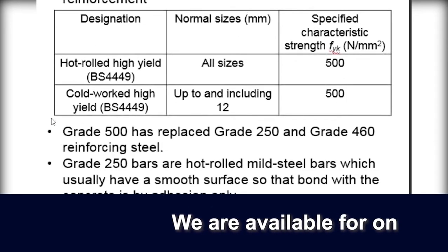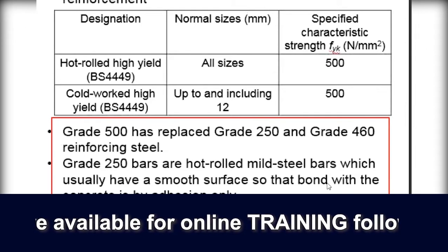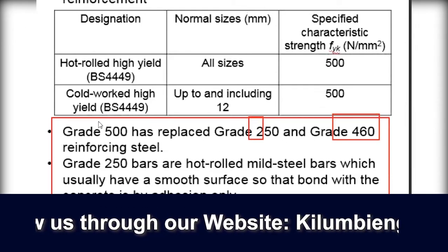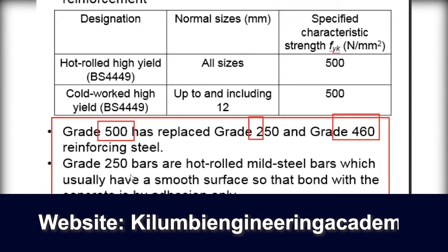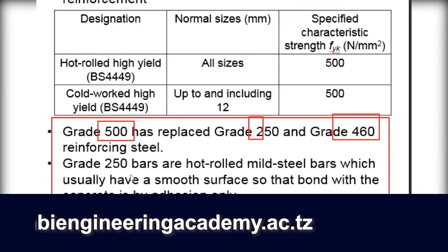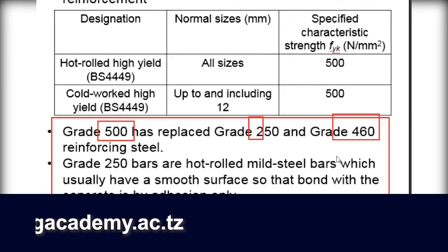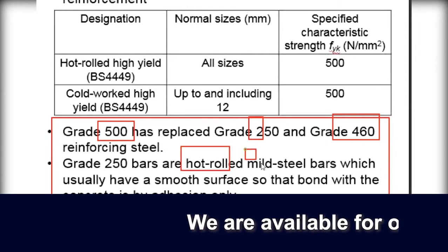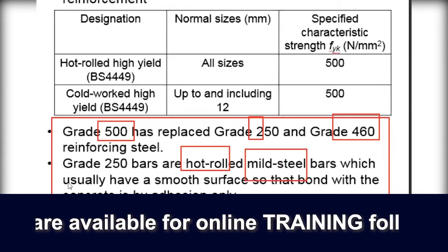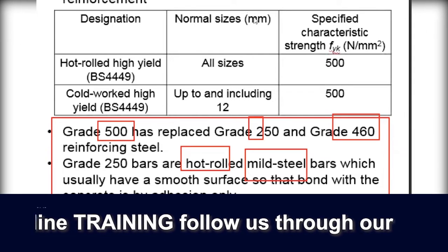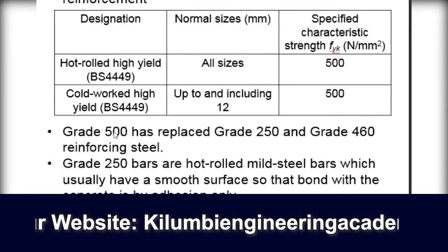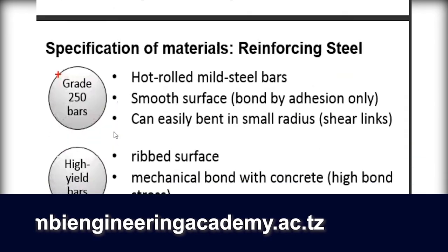So it means the yield strength is about this one to this one, but in Eurocode they always use 500, while in the other way you can use up to 460 in designing, and it depends whether it is hot rolled steel or cold worked. So it is up to you to pass through and look at which kind of steel you use in your design specification.